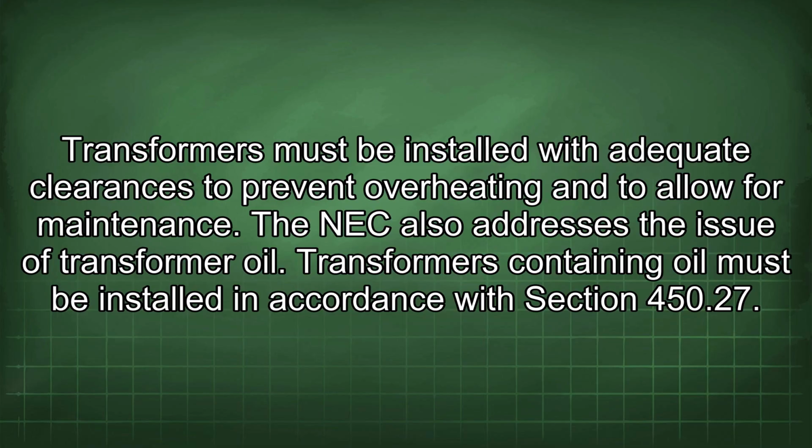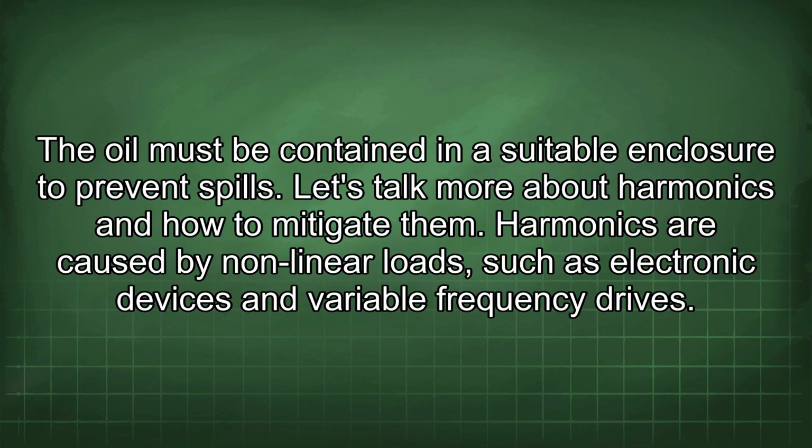The NEC also addresses the issue of transformer oil. Transformers containing oil must be installed in accordance with Section 450.27. The oil must be contained in a suitable enclosure to prevent spills.